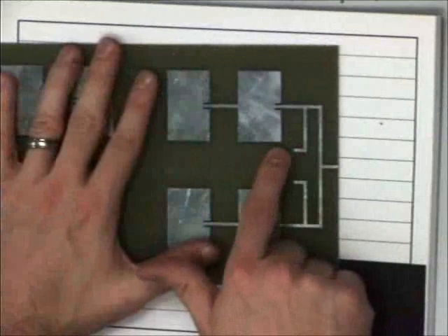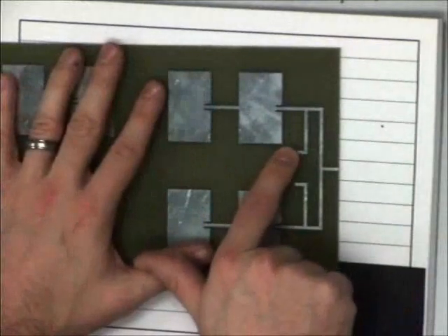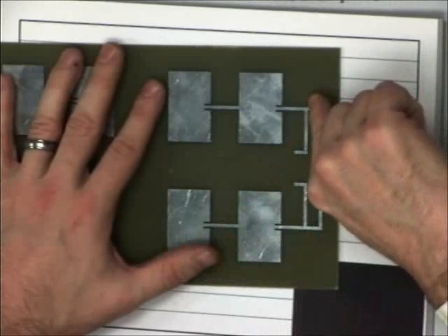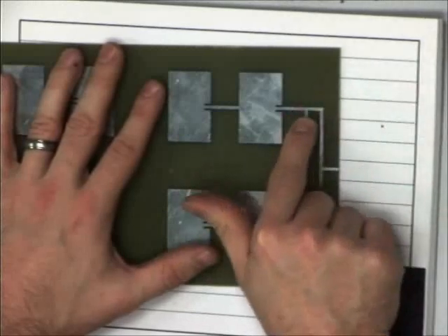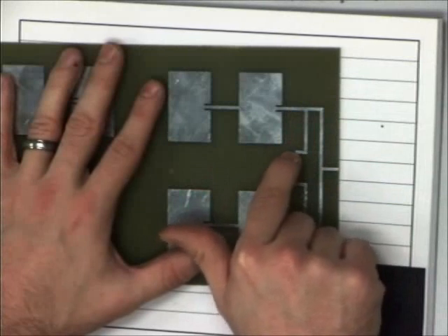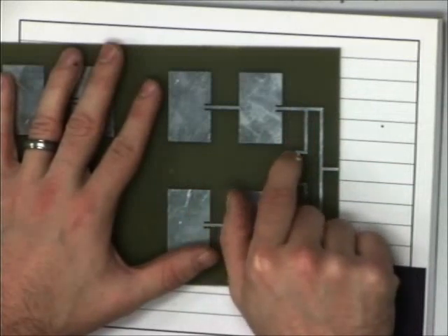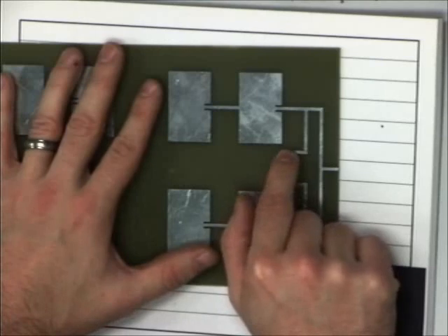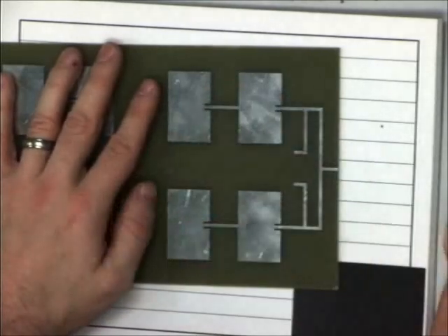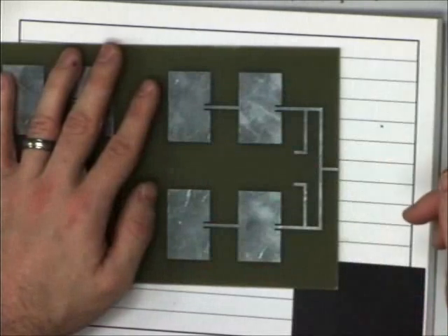And so the students that did this put in a little clever backdoor for helping tune their circuit. This is called a stub line. You see, it's a parallel fan-out line of a certain length, and it terminates into nothing. Now, in open circuit, the center frequency of this thing looks to be about 2.45 gigahertz, so it'd be like Wi-Fi radiators.